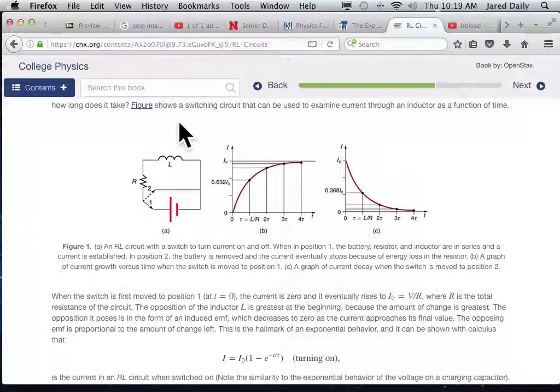So this right here is a slow turn off, turn on system. If you want a system to turn on slowly and to turn off slowly, just put an inductor in there. And the size of the inductor will determine the speed of the turn off and turn on in your system. How much inductance it has. More inductance will turn on slower and turn off slower for a given voltage.